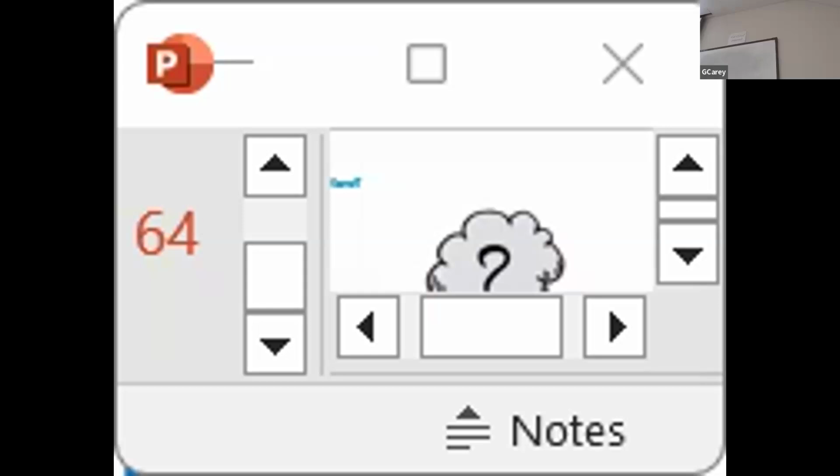So when I say I'm variable speeding, this is my bottom rail. I'm not going to go below this. But from that bottom rail up to my design conditions of, say, that 100 feet, I'm going to vary, and that's where my energy savings is going to take place. But I'm not going to go below that point to honor that control valve pressure drop in that terminal unit, and that far reaching unit, if you will.